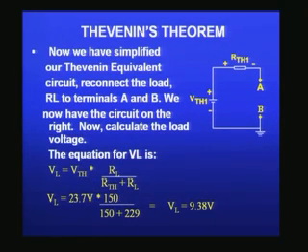Now finally, to obtain the voltage across the load RL, we will put all the things together, V Thevenin, R Thevenin, and measure what is the voltage across AB. VL, the load voltage, is equal to V Thevenin, which is 23.7 volts, multiplied by the potential divider RL divided by R Thevenin plus RL, and when you do that simplification, you get around 9.38 volts. So we can actually put the circuit on a breadboard and measure once again as we have done in the previous case.